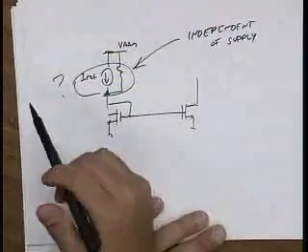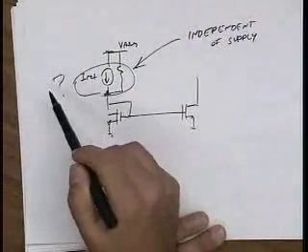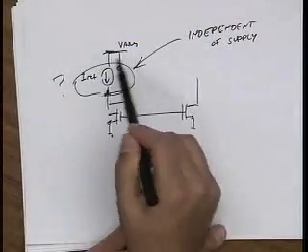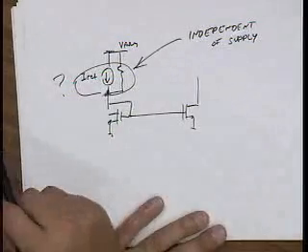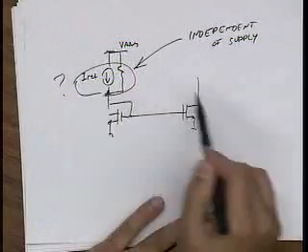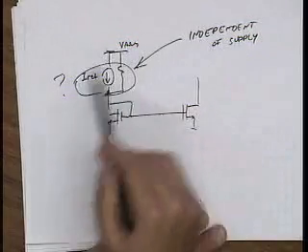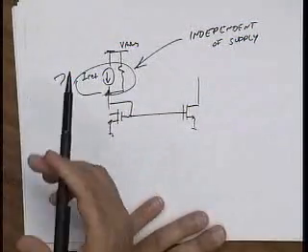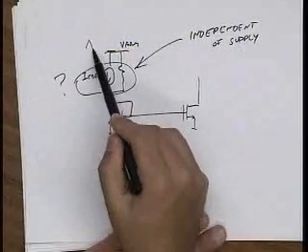The battery voltage changes, right? One day it's 3 volts, the next day it's 2.7 volts. Talk on the phone for 30 minutes, the voltage drops on your battery. So there's natural variations, and if the bias currents change significantly with supply, it's going to be a bad idea, right? But also there's noise on this.